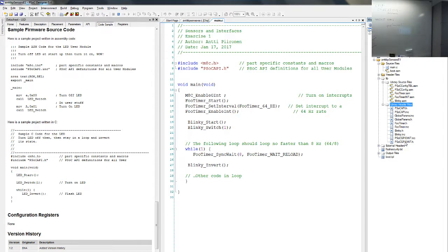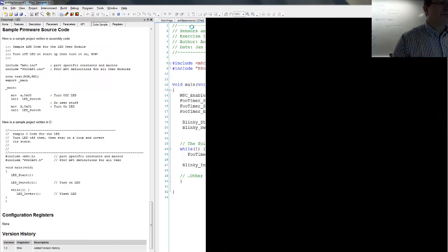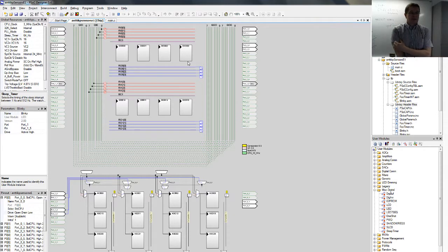So basically for the input, you need to make the input pin actually a pull down mode. Or you can add an external resistor to the circuitry. But anyways, you need that one. This one itself doesn't work. It's just a connector. It's just wire. Okay, so how to make that? Let's go back to the chip design.